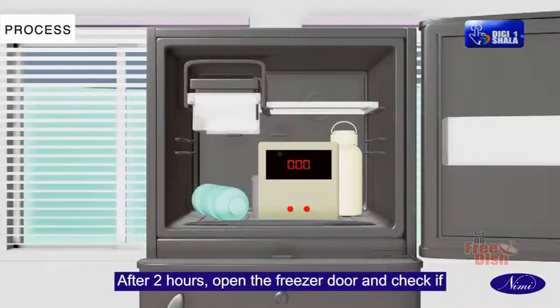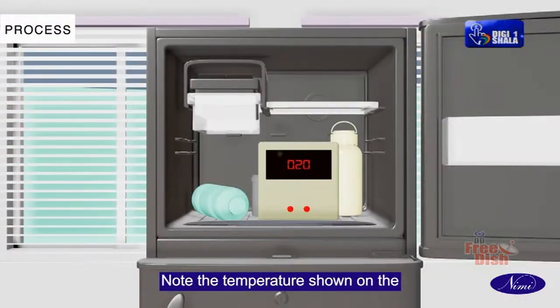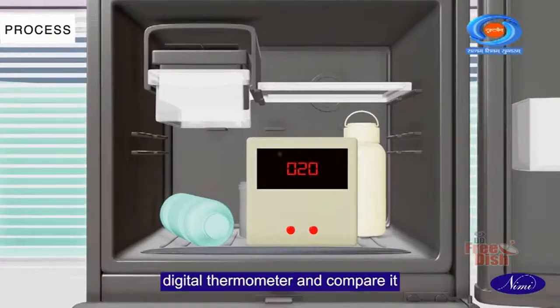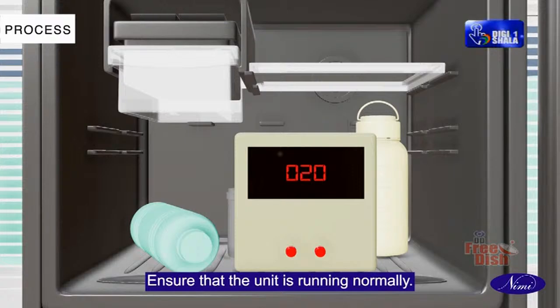After 2 hours, open the freezer door and check if the water in the ice tray has become solid ice. Note the temperature shown on the digital thermometer and compare it with the initial temperature. Ensure that the unit is running normally.